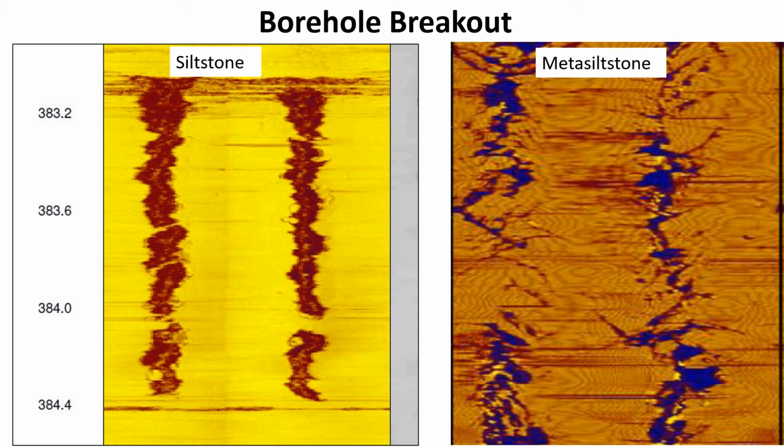More detailed analysis of stress from breakout requires additional information such as might come from the minimum stress measured by hydrofracture and the compressive strength of the rock perpendicular to the hole axis. Determining this compressive strength is difficult to achieve with certainty, and it is generally better to treat borehole breakout as an index of stress to strength ratio that also provides information on stress direction.